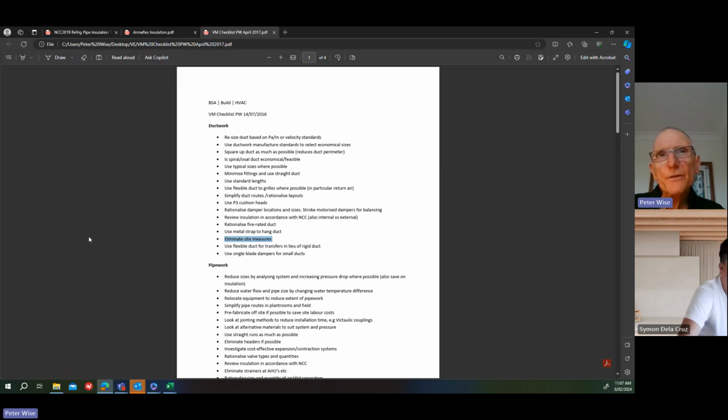we used to try very hard not to totally eliminate them, but to really minimise them because it's quite expensive to make site measures. The process is that the tradesman on site has to measure everything he needs, the length and the angle and all that. And that's got to go back to the factory. They have to hand make it and then send it to site. It slows down the process on site as well because they can't finish the job until they get the site measure made. So it might take a week before they get it back from the factory to install it.